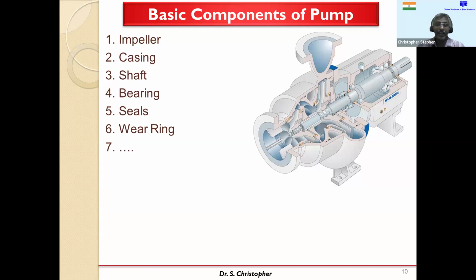So if you look at your drive, drive is also important, and then seal. Many people are giving impeller, bearing, seal, and so on. Whatever you said, all the things are necessary, because everything works together, and only then can we get the required hydraulic head, even the casing, because without the casing we can't convert the kinetic energy